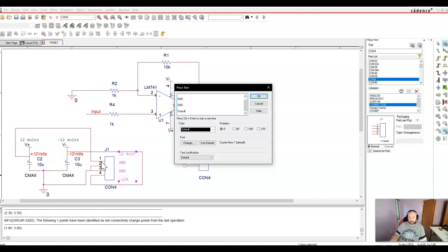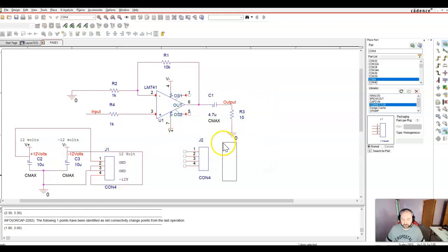And then the output, your headset, is the output plus ground, because there's 2 wires, well, 3 wires for stereo, but there's 2 wires for a speaker. One you can kind of think of as ground, and the other you can think of as the actual input. So I'm going to still have that like that.